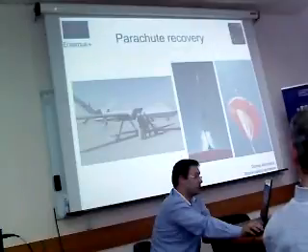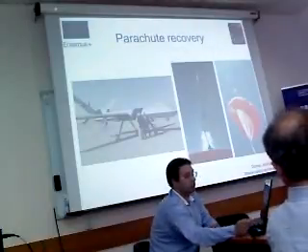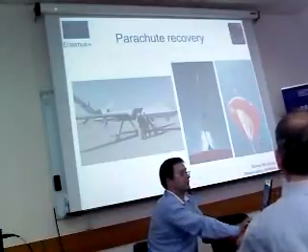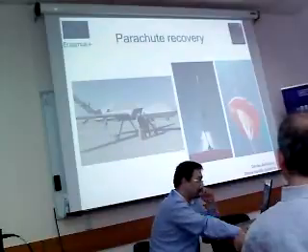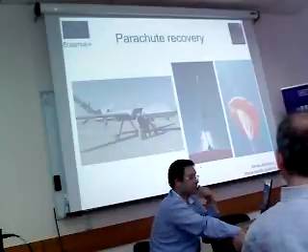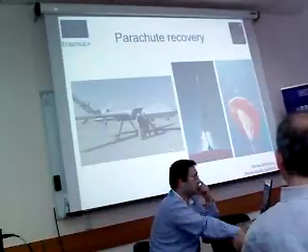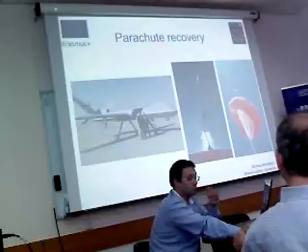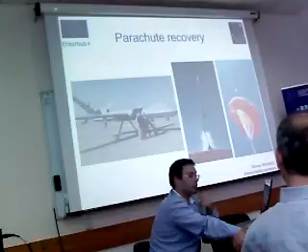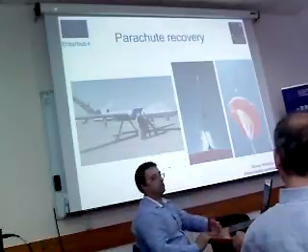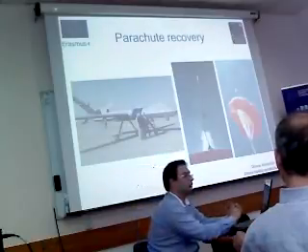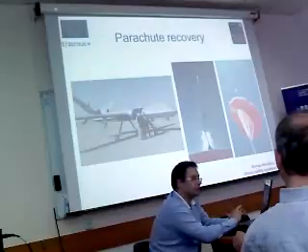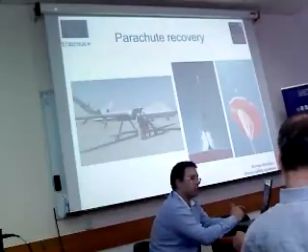So for the large UAVs, there are different ways of using the parachute. In particular, it depends on the UAV design. For example, the Predator UAV has a normally pusher prop, so it requires the use of the forward deployment method to ensure that the parachute will clear the prop. So there is a tractor rocket system that was selected for a crossing deployment of the main parachute.